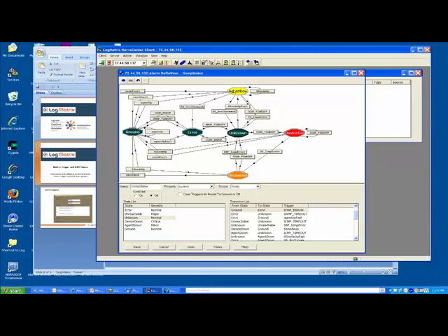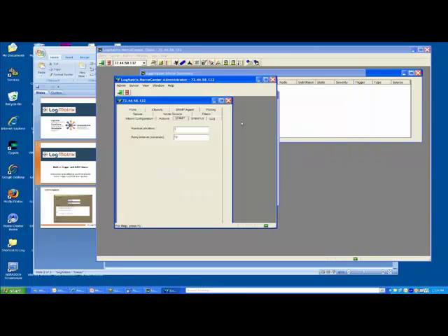Built-in triggers. Let's talk a little bit about this. Let's say I've issued a poll request and it times out. I wait 10 seconds. I issue my first retry request. It times out. Then my second, it times out. And then my third, it times out. How much time has transpired? If you add all of those 10 seconds up, it adds up to 40 seconds. 40 seconds before that alarm should issue a new poll.